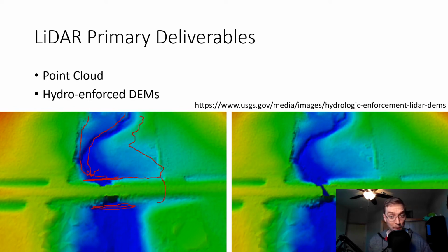So it would spill over it, but that's not actually what's going on. We know that that stream is flowing underneath the road. So hydro conditioning or hydro enforcing basically says, okay, we know this is a road, and to accurately flow, we're going to cut right through that road and act as though the stream was flowing through it. It's just what we call stream burning, or hydro enforcing, hydro conditioning. We're basically just taking this road and cutting right through it with our stream, so that when you're trying to do flow reconstruction, the stream is flowing the direction that it needs to go.